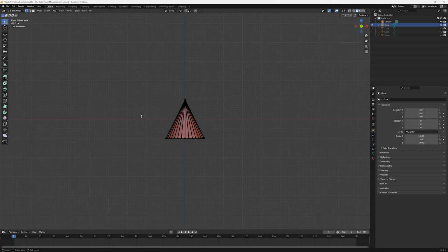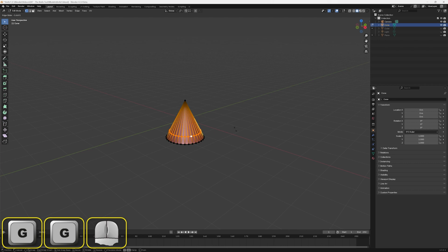Rather than select the knife tool from the toolbar, we can access it using the K key as a shortcut. But if we use this option, there are no control fields in the top left of the 3D viewport. One last point to remember is that we can use the knife cut to cut through any type of face: tri, quad, or n-gon. So, while the loop cut will not cut through a standard cone because its sides are tris, the knife tool can do this without any problem, and we can use GG to slide the new cuts to any position.